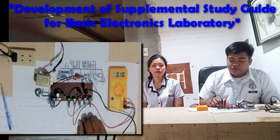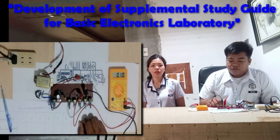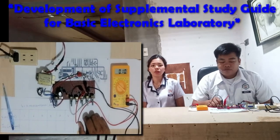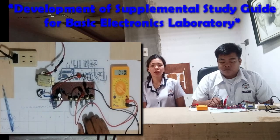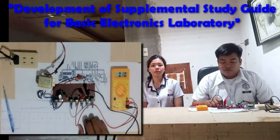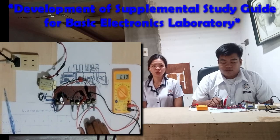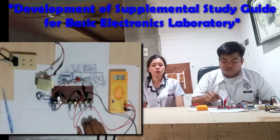The base current could have been measured with an ammeter, but that would require opening the circuit path and inserting the ammeter in series with R2 and the transistor base. Remember that any time we add a resistance in series, the current decreases, since we only have 10 microamperes of current flow in the circuit. It is not a good idea to introduce unnecessary loading in the circuit.